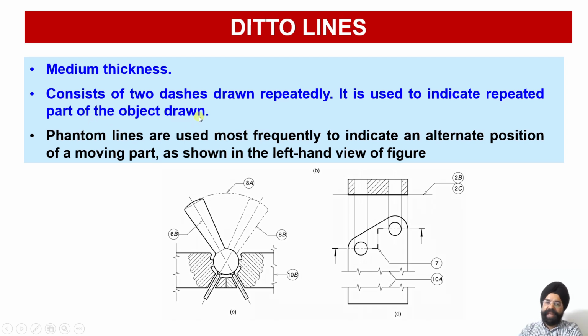You see, there will be many instances where in any given machinery there are moving components. When the machine is idle or at a standstill, this is the component in the idle situation. But when the machine is working, this component or handle may be moving to another location. So why do we need to show this? Because I cannot plan any other component or activity into this area.